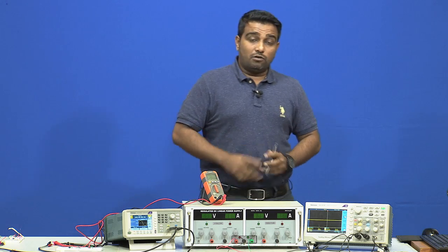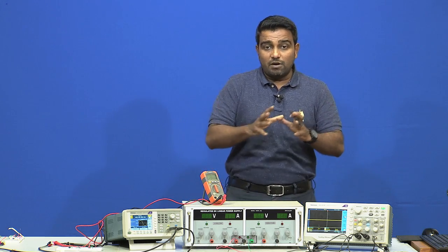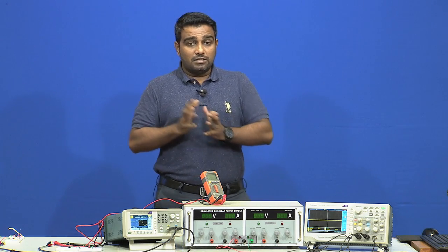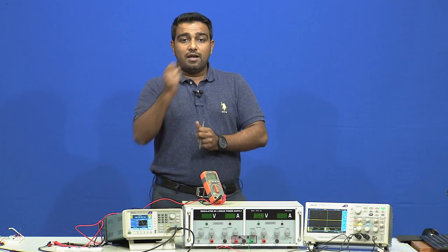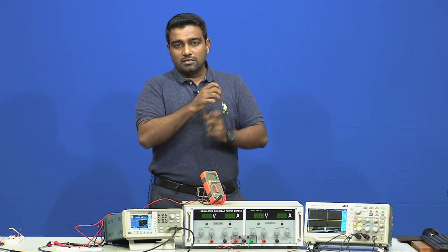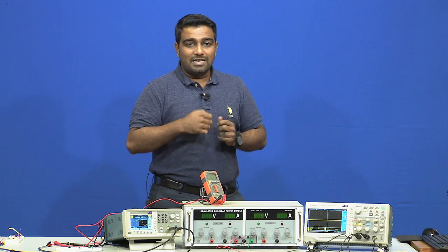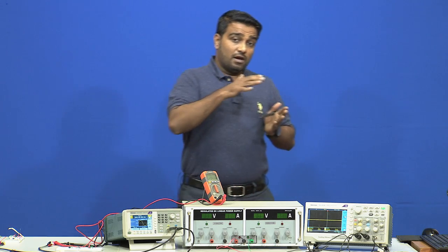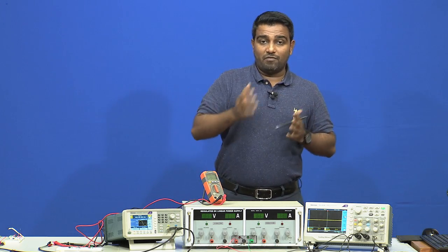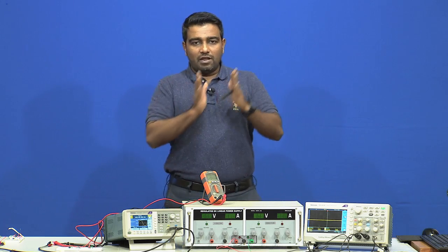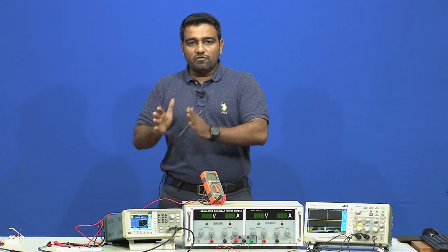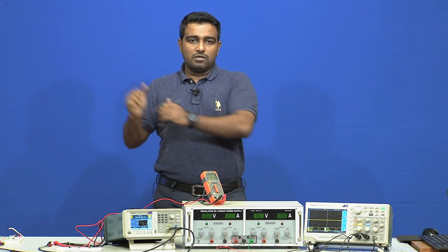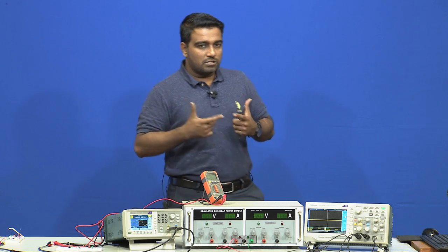To make the amplifier stable, to adjust the signal, we need to apply negative feedback to the circuit, then only we can adjust the gain, or play with the gain, and it becomes an inverting amplifier or non-inverting amplifier. Negative feedback will give us amplification, positive feedback will give us oscillation, right. We have seen both things in the class, so just to recall it.